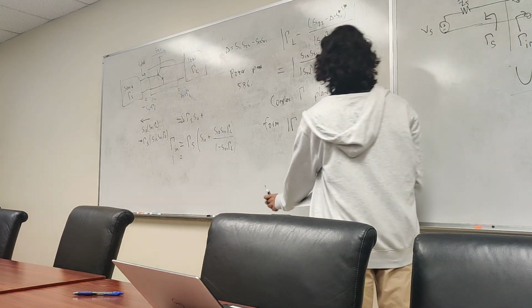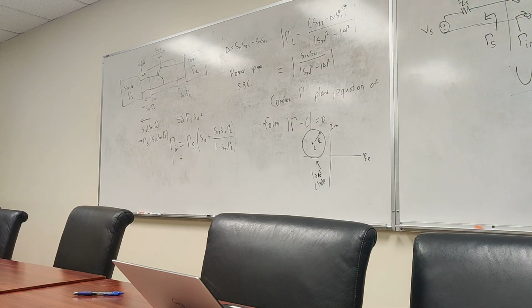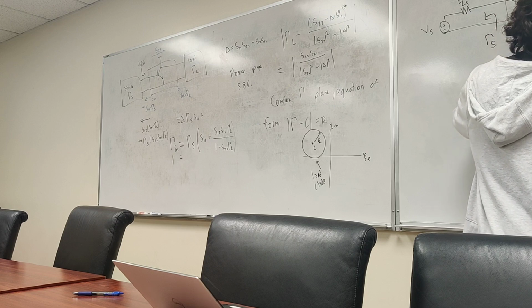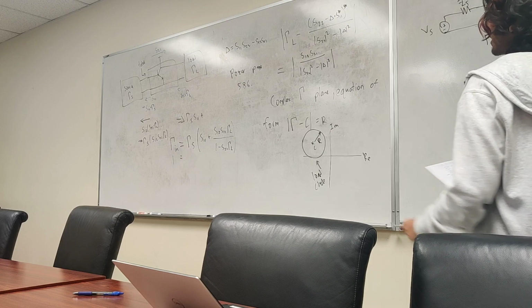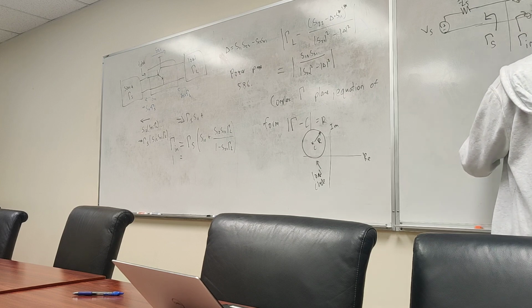There has to be an easier way to figure this out, right? So plotting a circle, going to a Smith chart, doing all that work, why even bother, right? Is there an easier way? And it turns out there is. It's a much easier way of doing so. It's called the K delta test. And the idea behind this is let's abstract away all these terms into two variables, K and delta. And how big these K and delta terms are will tell us how stable we are. Okay. So we have unconditional stability.